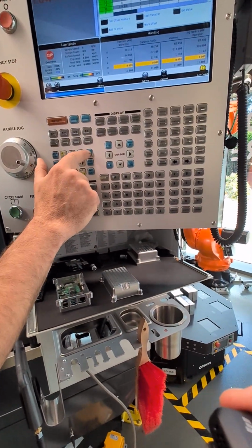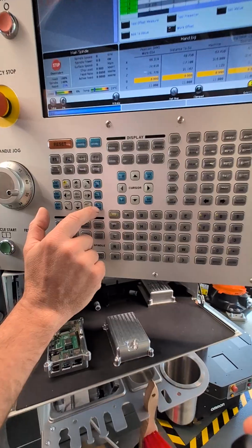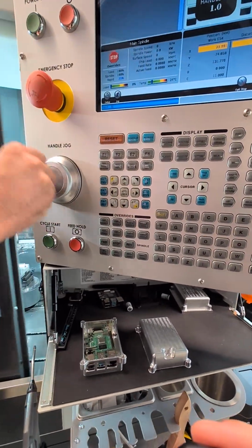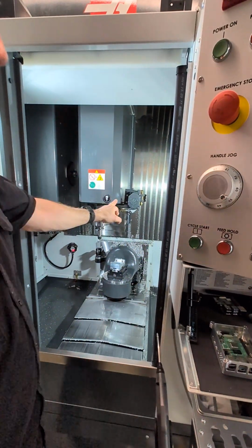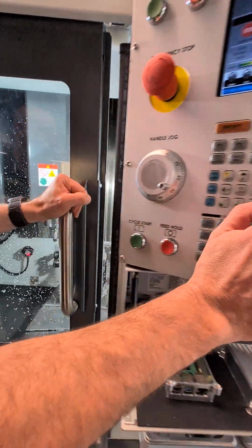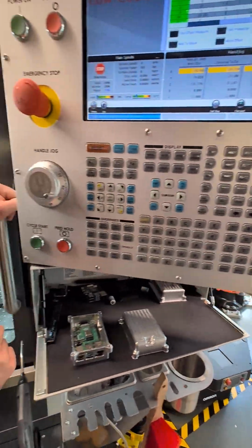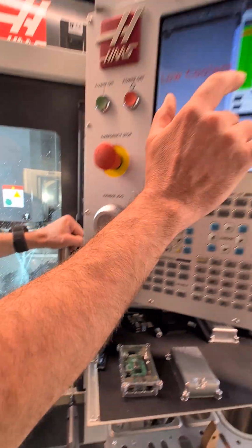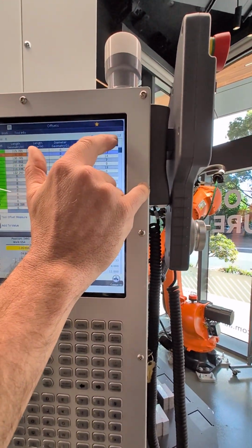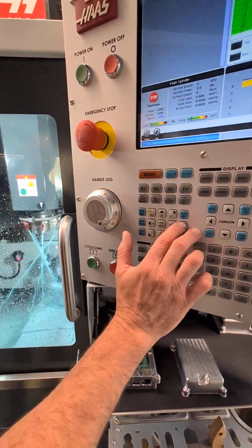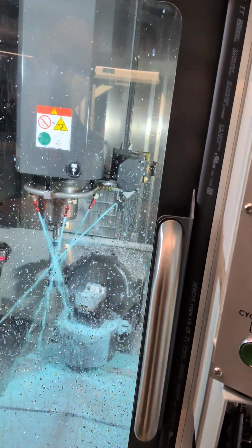Now over here we've got coolant up, coolant down, and auxiliary coolant. So over here, this is controlling your programmable coolant nozzle. If we turn the coolant on with the coolant button, you'll see it obviously shoots out at an angle. Now, if you look up here on the offsets page, it's got coolant position of 12. Well, this is a 34 position unit. So if you press down, you can control it and go back up.